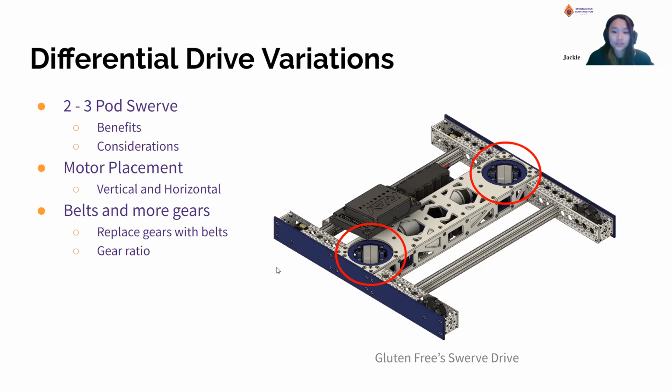We have a question. Would Onshape work well for a CAD software, or would you recommend Fusion 360? So one thing we noticed is because Onshape is a cloud website software, it is great for making really quick custom parts. But when it comes to actual assemblies, if you have larger things like entire drivetrains that have a little bit more complexity in them, it does take a while to load that up. Another benefit that both Fusion 360 and Onshape have is the cloud sharing, so we can have multiple people working on parts at a time.